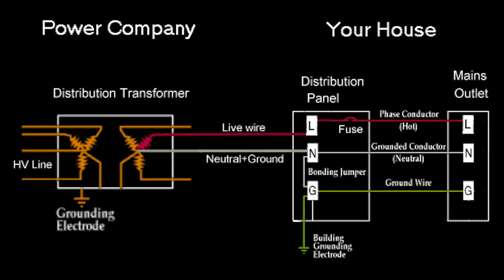Most households receive power at 120 and 240 volts. Business customers may be supplied with single-phase or three-phase power up to 480 volts AC. Some business customers provide their own distribution transformers, which are supplied directly from the primary distribution feeders. As close to the customers as possible, the primary distribution voltage is stepped down by distribution transformers to secondary voltages that can be used by customers.